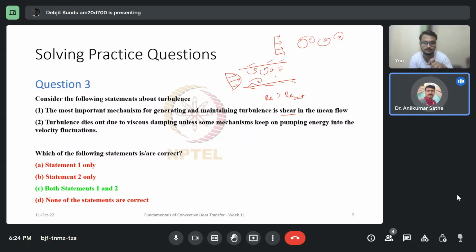What I have done was in forced convection. I used air as a fluid. I manufactured a tube-in-tube type of heat exchanger. In the center tube, I circulated air from the blower, and in the surrounding tube, I circulated water. Inside the center tube where air is passing, I put one central rod, and on that central rod I arranged different fins at different angles.